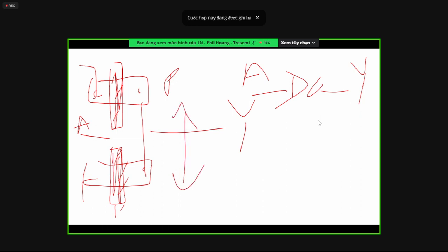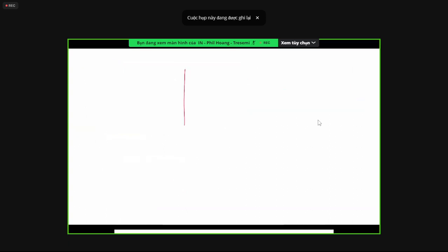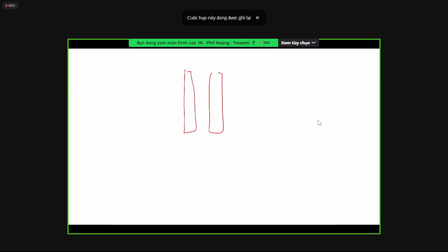But in your macro, you have transistors too. So your macros will have certain orientation, but for certain technologies, because of process control, all the poly have to be in one orientation, otherwise the process control will be messed up.